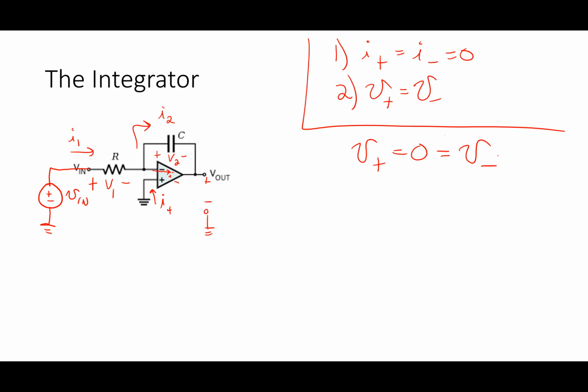So I can do a nodal analysis again at the exact same node to get the gain relationship here. How do I do the nodal analysis at that node? How do I write this? I1 equals I2. Then I have to put this in terms of, sorry, Ohm's law. So what do I say? Well, it's V1 divided by R. That was straightforward. What about I2?